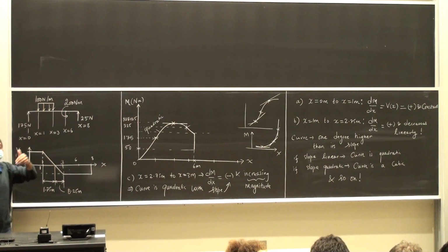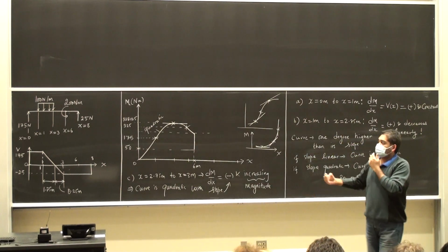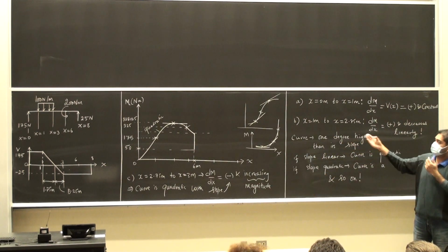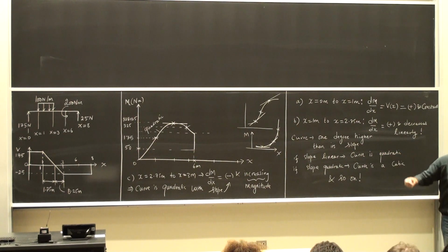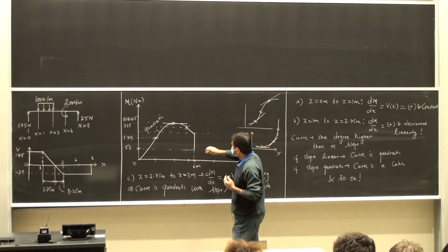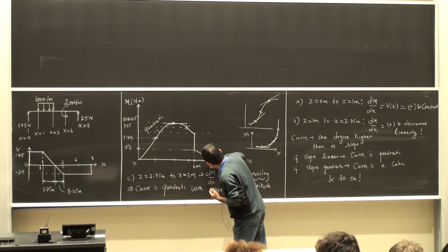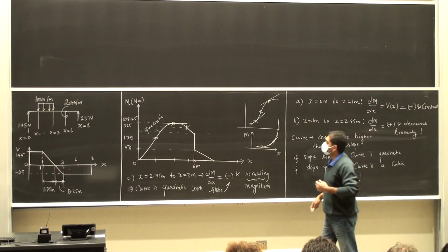That's the discontinuity in this bending moment curve. And then I go back home in the same manner as I started, from 6 to 8. I see that the slope of the shear force diagram is negative and constant, which means the value of the shear force is negative and constant. So I drop off in this particular manner. Okay, so this is from 6 to 8.